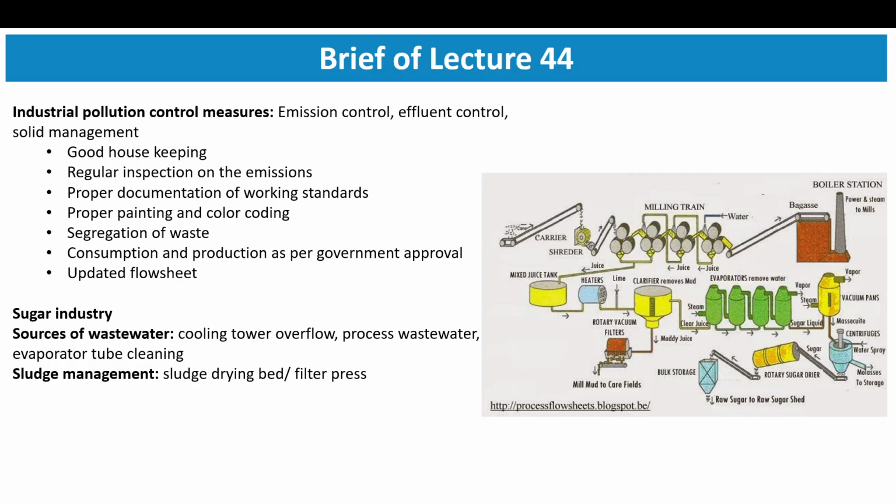Next is segregation of waste. Segregation of waste is important because you wish not to mix two contaminants, as it will increase the volume. For example, if 20 liters of water with lead contamination is coming out of one reactor, and another reactor gives 30 liters of water with organic contamination, and you mix these two waste streams, the pollutant types are different and need different treatment technologies.